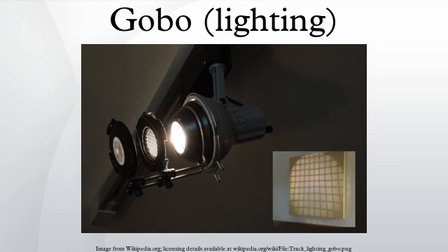In the past, plastic gobos had been generally custom-made for when a pattern is needed in color and glass does not suffice. However, in a traditional light fixture, the focus point where a gobo must be placed is usually extremely hot, so these thin plastic films generally need to be used with special cooling elements to prevent melting them. A lapse in the cooling apparatus, even for just a few seconds, can cause plastic gobos in a traditional lighting instrument to be ruined.